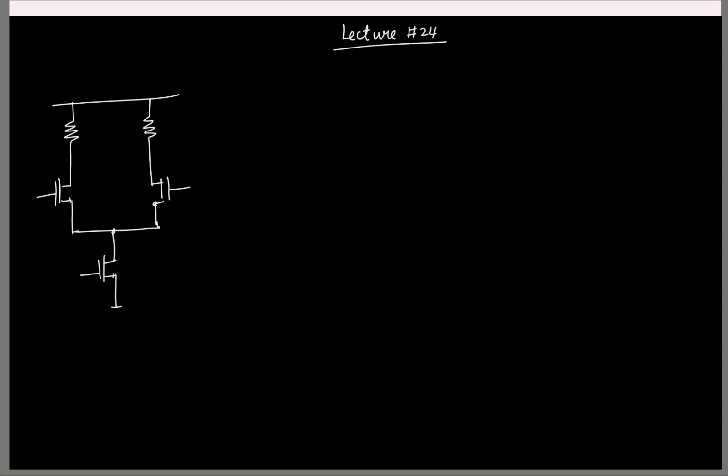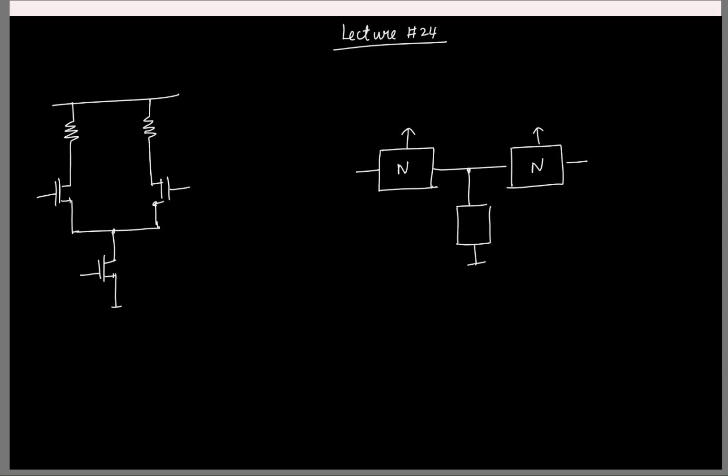And in general, a fully differential circuit might look like this. So we'll have two identical copies of the network. So here is where we apply the input, and say the outputs are taken here, and you will have some network in common like this, say NC or something. Okay. So now if I apply a differential input like this, what will be the differential mode half circuit? I'll have N here, so the right side is grounded, so I'll apply the input here and take the output here.